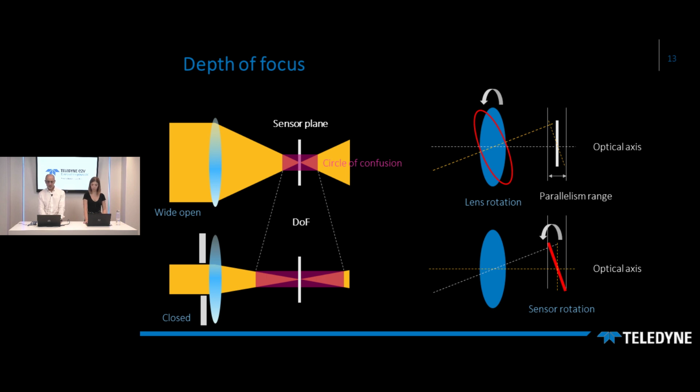As illustrated on the figure on the right, the optical and the sensor alignment are subject to mechanical tolerance, especially when assembling the chip in the package or the sensor in the camera. Sometimes there can be both misalignments at the same time, which together lead to a focal plane parallelism defect. It is important that the depth of focus is within this range to ensure that the image is sharp at all points of the pixel array.